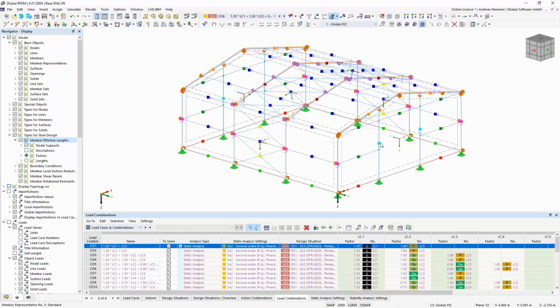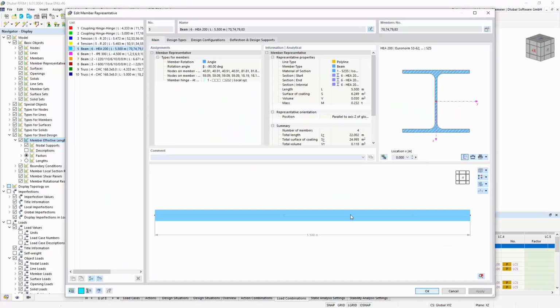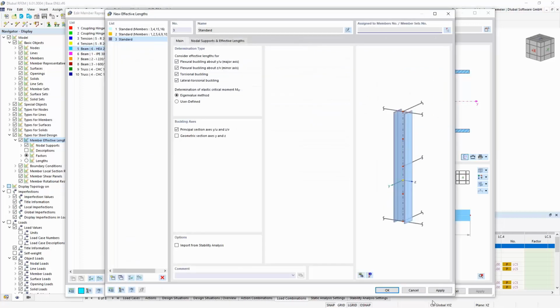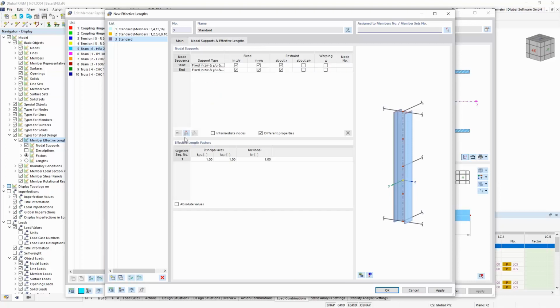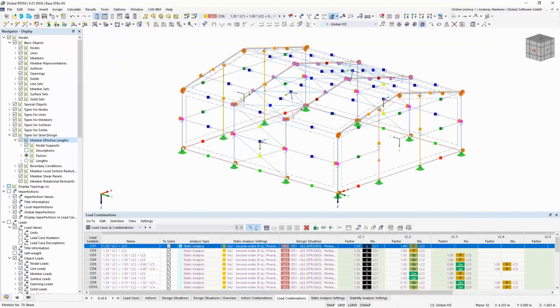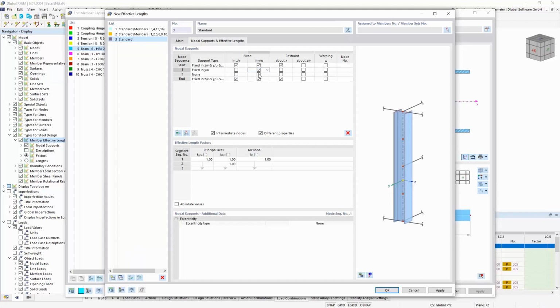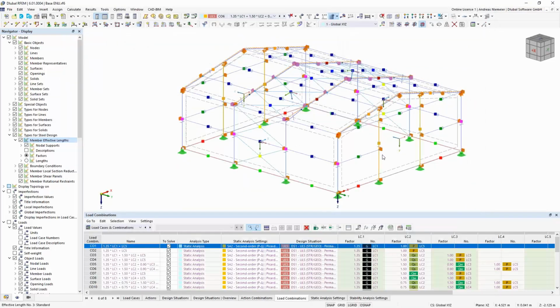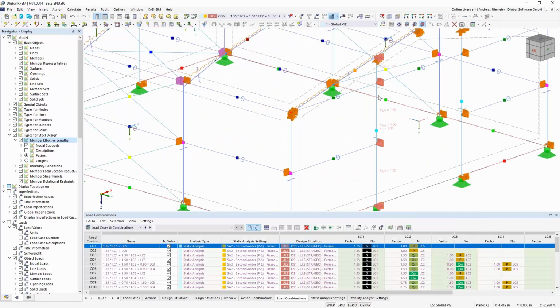Now these roof gable columns are missing, so we can also add here effective length setting, maybe here to consider, let's say, at least these intermediate points. And you see this is maybe done also for these elements, and he always places these supports on the nodes what are available in the member.